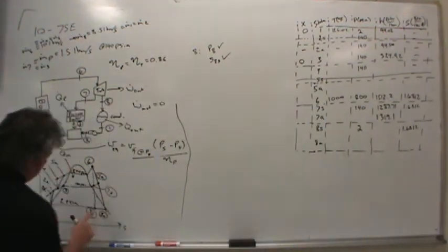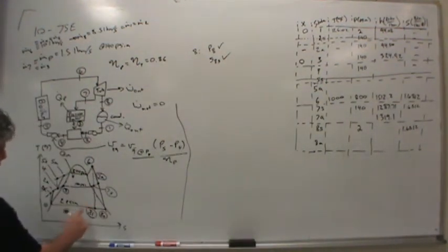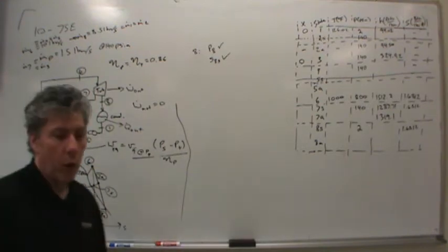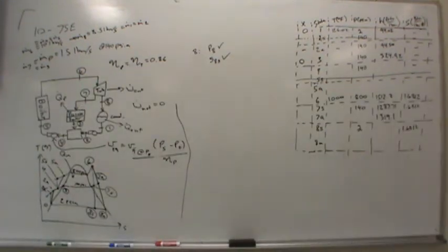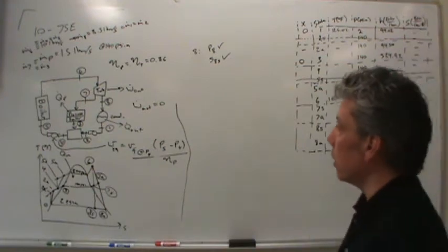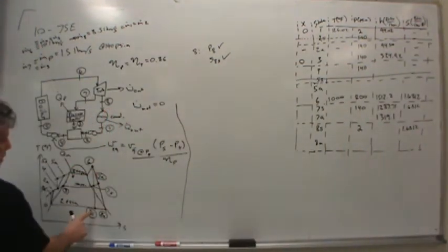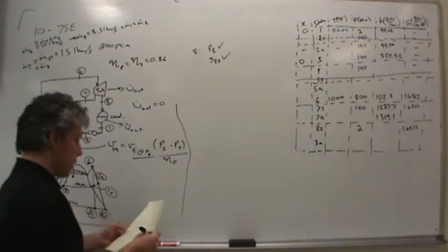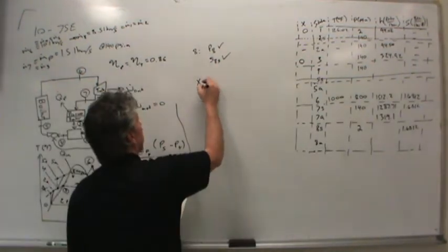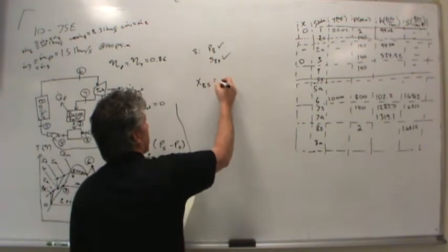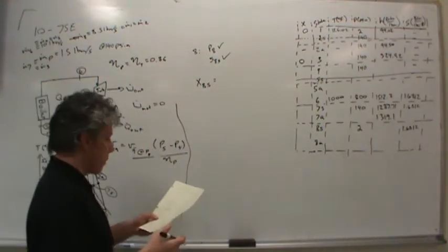That means me putting this point inside of the vapor dome is correct. There would be a quality, in other words, a fraction that is in the liquid phase in state 8S. And so I should first of all begin by calculating the quality, or in other words, simply the percentage that's still in the vapor phase.